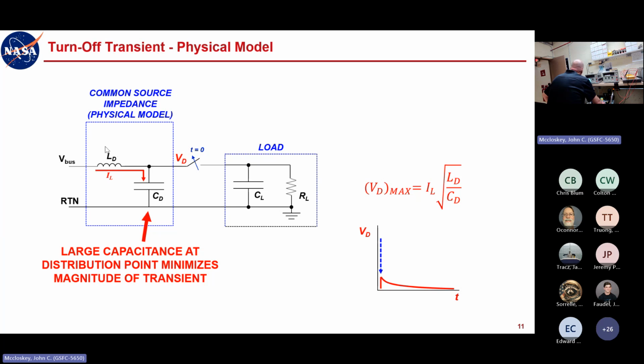So there's probably substantial inductance there without a huge amount of capacitance. I mean, you'll have the transmission line capacitance just from that wiring, but the Z naught of that kind of construction of a transmission line is going to be on the order of 50 ohms, give or take, maybe between 50 and 100 ohms. So what that means is that if you're pulling an amp of load current before you throw the switch, and let's just say your Z naught is 50 ohms, well, you could have a spike of 50 volts.